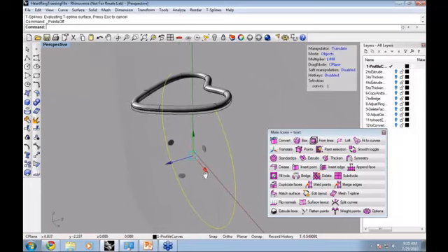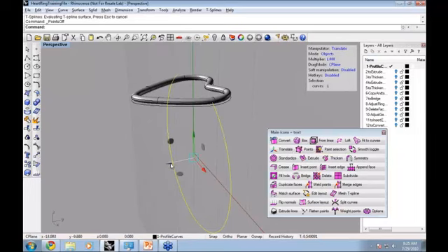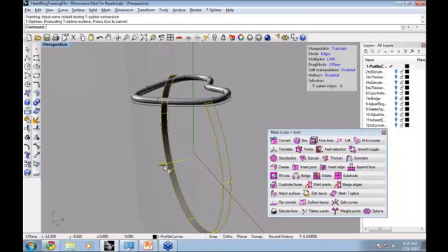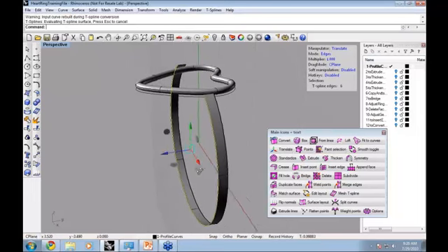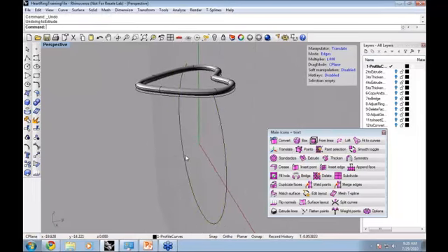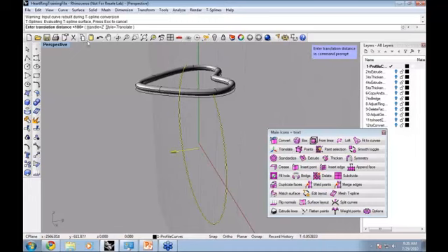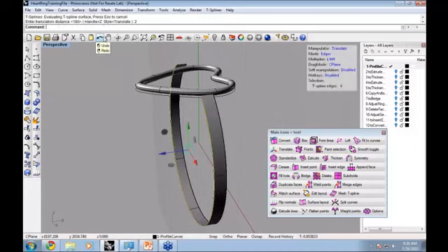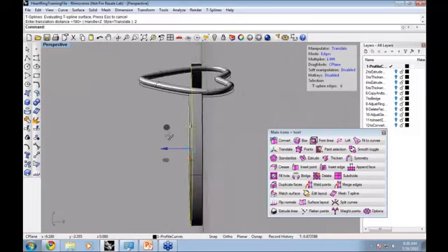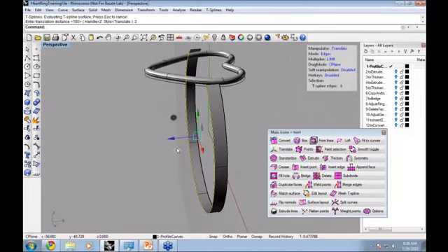So I'll do that same procedure. I'm just going to hold down Alt and drag to get some distance here. And by the way, I've just been freehanding this, but if I undo this and double-click while holding down Alt, then it lets me enter an exact distance for how long I want this to be. So let's see what 2 gets us. Not too bad. So this is 2 units wide now.